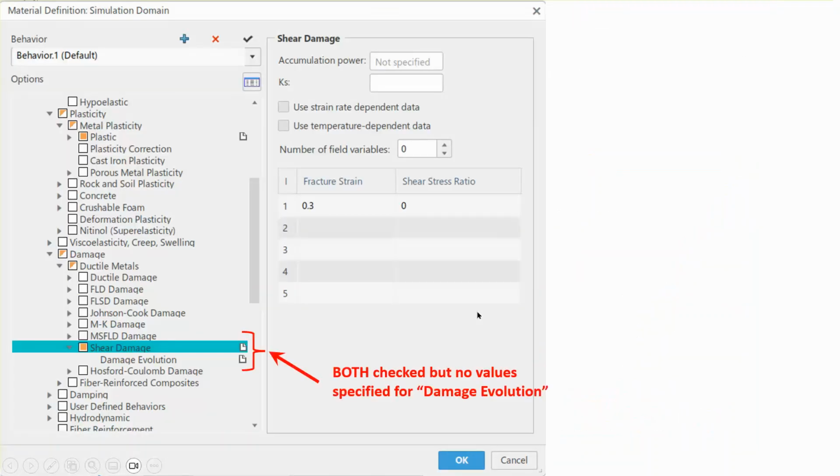Keep in mind that in tutorial 7 I mentioned that in order to replicate the damage, when it comes to damage criteria, you have to actually ask for both of these lines. Both of these lines have to be requested. If you don't request the last one, the ball will not go through the plate, and it just carries the plate with it. In other words, the failed elements do not actually show. The last maybe 1 minute of tutorial 7 displays that and tells you what it means.